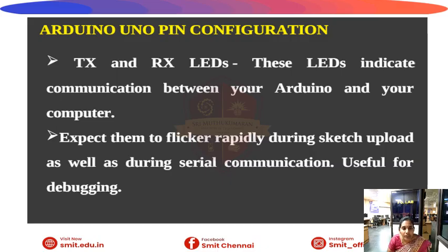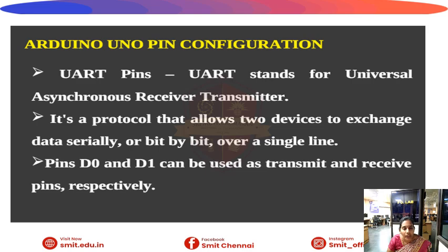Next, transmitter and receiver LEDs. These LEDs indicate the communication between your Arduino and your computer. Next, UART pins. UART stands for Universal Asynchronous Receiver Transmitter. It is a protocol that allows two devices to exchange data serially, bit by bit, over a single line. Pins D0 and D1 can be used as receive and transmit pins respectively.